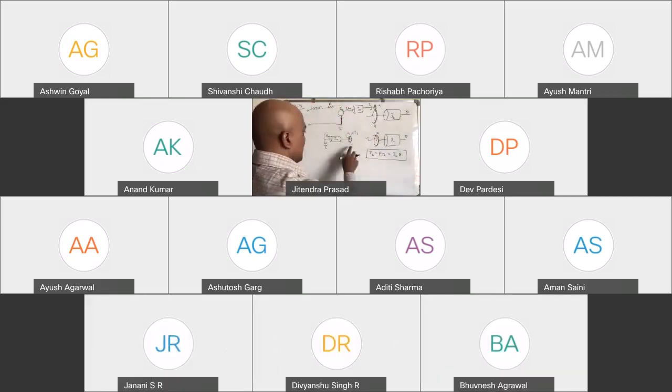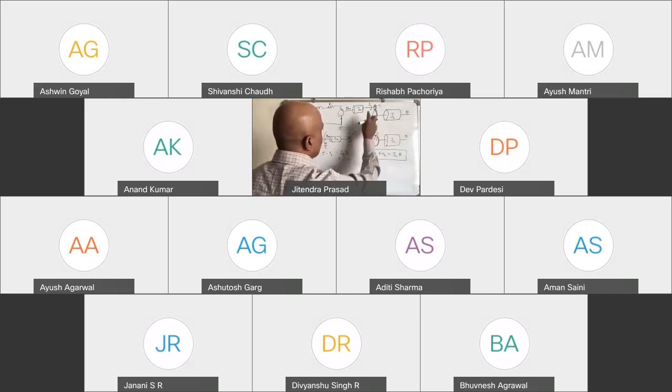Okay. Now write the equation. The equation will be tau minus tau 1, which is the total torque acting on this one, and the equation should be Jm theta m double dot. That's what it will be, right? So this relates to this one. How? There tau 1 is equal to F, the same F we have, times R1. R1 is the radius of this gear.